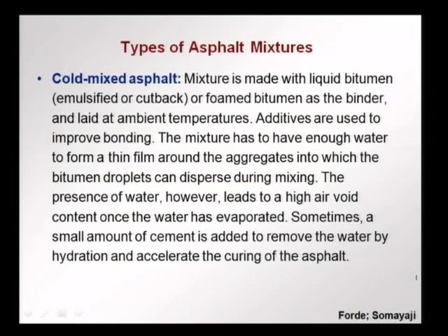Liquid bitumen could be emulsified, which I just mentioned, where we have bitumen and water in an emulsion form. This is kept stable by the use of an emulsifying agent, or we can have cut back bitumen. Cut back bitumen is where bitumen is dissolved in a solvent, and that again facilitates the fluidity of the bitumen, and in both cases the evaporation of the water in the first case and the solvent in the second case allows the bitumen to settle and bond and give the asphalt concrete the matrix that it requires.